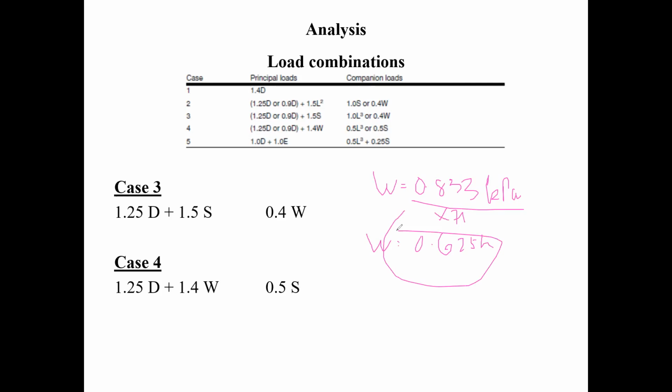And don't forget, when you're doing your design check, you have to check for strength, you have to check for shear, and you have to check for deflection, just like we did in the assignment in your project. And so how did they come up with these values? Well, I just showed you step by step how they came up with those values. So in an example, they just throw them at you, but in real life, you have to calculate your W. And that's how you do it.